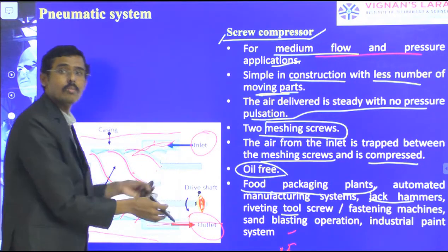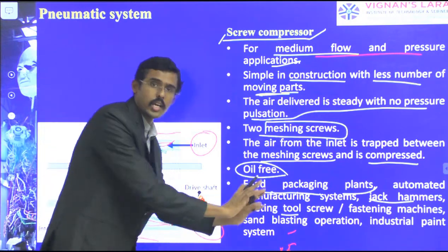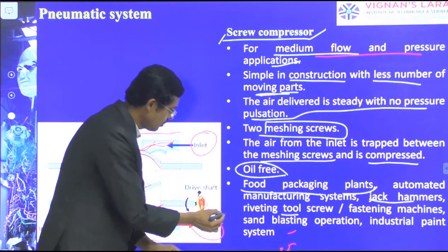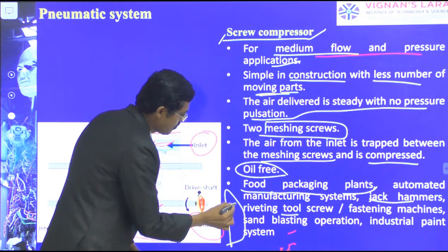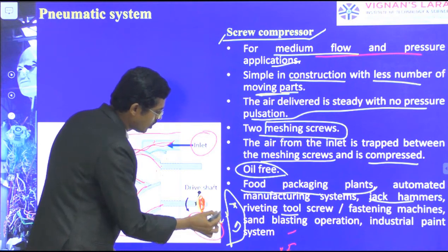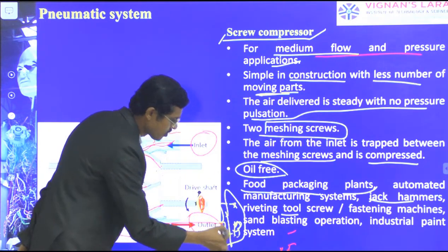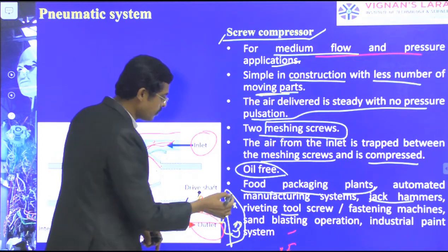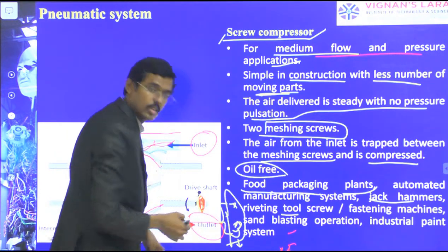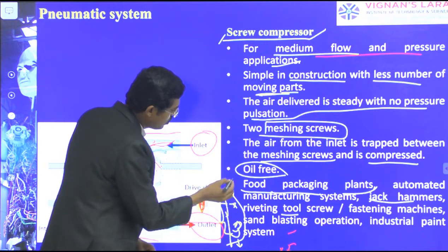This is to be controlled by the load. What is to be pressurized? Here we can have the control valve, maybe port A, port B. Whether this outlet is to be connected to A, or otherwise to B. Accordingly, if A is operated, the piston will move in the downward direction. If B is operated, the piston may move in the upward direction.